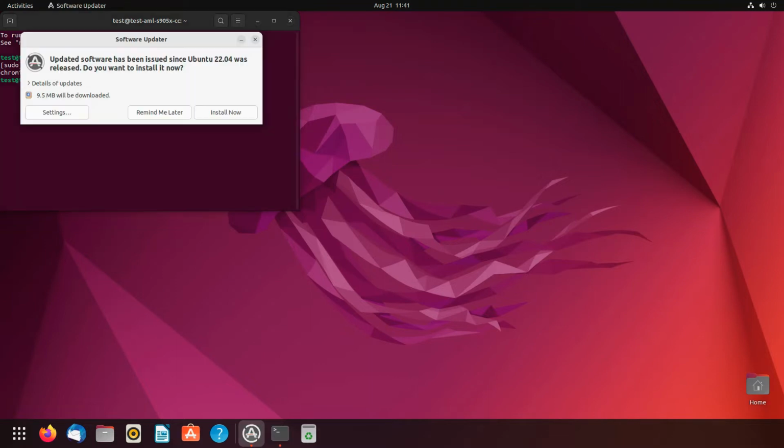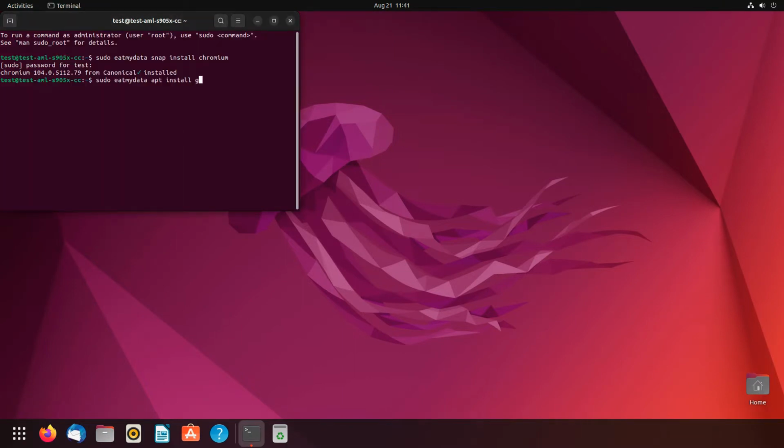To install a 3D OpenGL ES2 demo running on Wayland, run apt install glmark2-es2-wayland. Additionally, please install build-essential for the make application in order to compile the device tree overlays for a later demo.